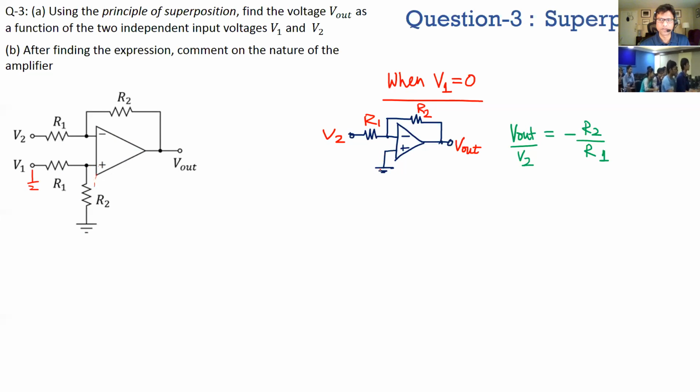So that's why you can see the positive node is grounded. And then you apply V2 across this. So this is nothing but an inverting amplifier configuration. And I would definitely encourage, you can obviously derive this, but when you're preparing for interviews, most people will expect you to know these kinds of configurations. So I will definitely encourage you to know inverting and non-inverting outputs directly.